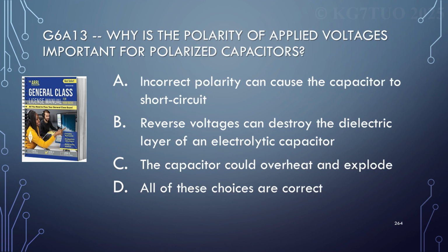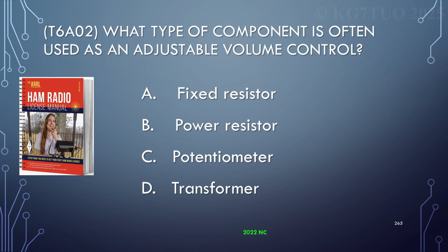Why is the polarity of applied voltages important for polarized capacitors? Incorrect polarity can cause a capacitor to short circuit. Reverse voltages can destroy it. The capacitor could overheat and explode. Are all those true? They are.